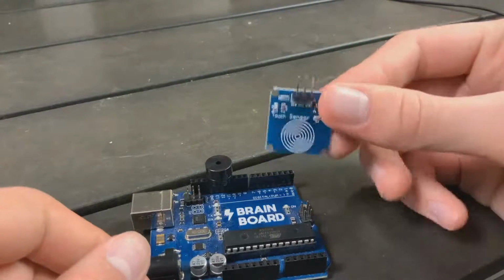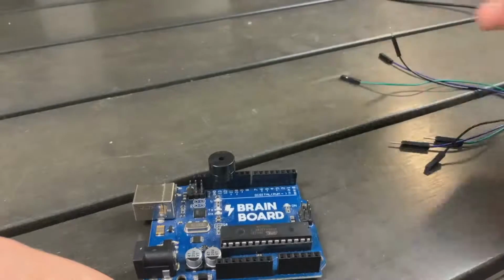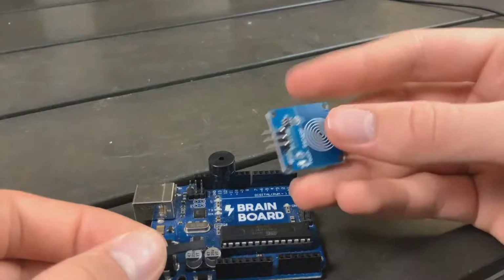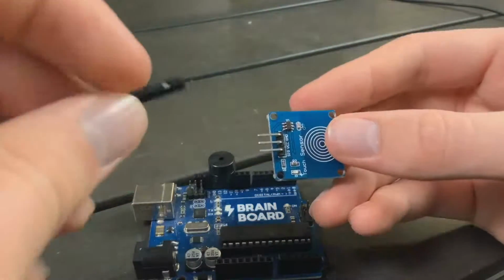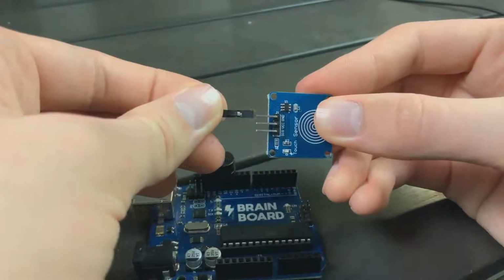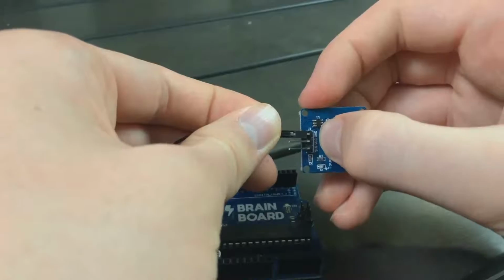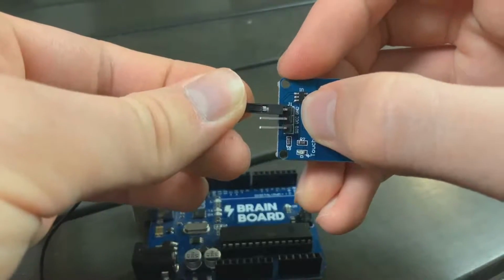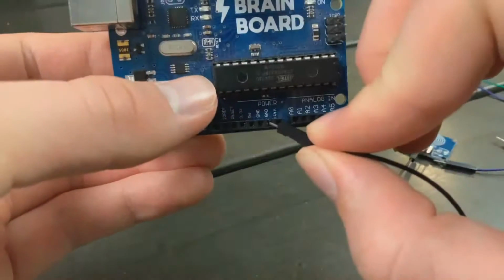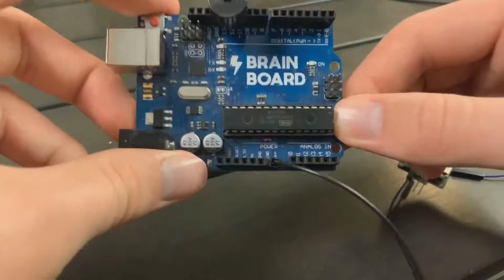The next part is to connect the touch sensor to the brain board. To do this, you will need your 3 wires. I'm going to get 1 wire now. Let's connect this first wire, get the end that is a hole, and slide it over the leg that says G and D. And you can see there are little labels over here where my thumbnail is, and these tell you what each of the legs mean. The pointy end, we're going to stick into the G and D pin over here on this side of the board. You can see that there are 2 of them and it doesn't matter which one you connect it to.